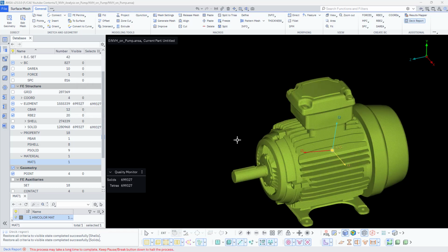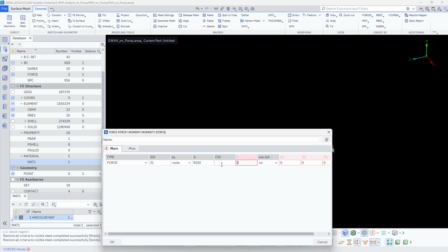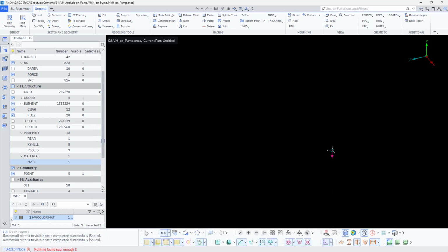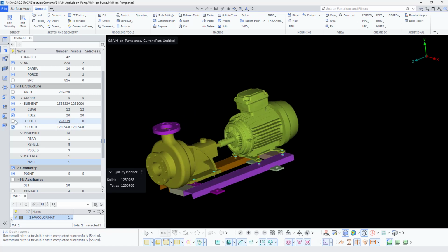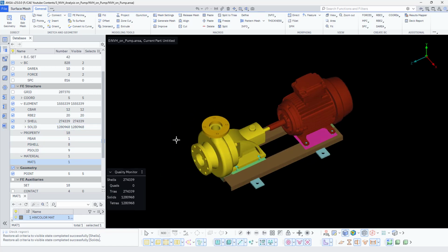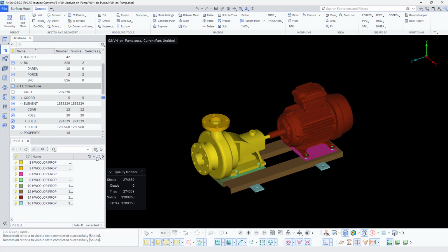You can even go for the visible also, that's fine here. 245 kg, so into 9.81, so approximately 2400. In the sense I can define it as 2500 Newton. So 2500 Newton, that is the reference point. Now, important: that particular COG point which we have considered should be connected to the mount and motor, right? So it is independent now. If you even excite it, that is also independent. Even if you apply the load, that grid is free and it will simply move the model.